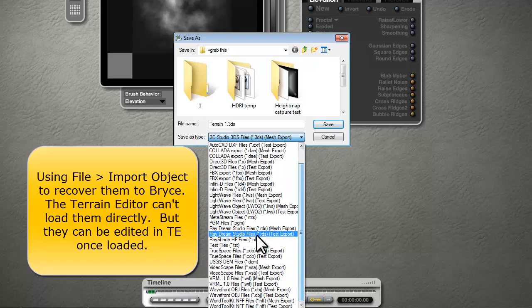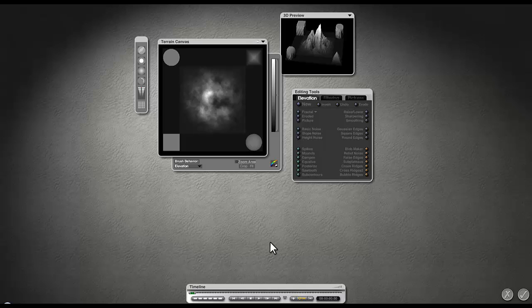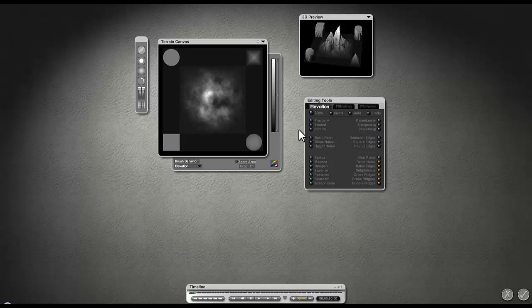So some of the height map formats do work, but the importer for the picture is very particular about what it accepts, and it won't necessarily accept back what you've exported out, but other software will accept it. What you need for the picture ideally is either 16-bit grayscale TIFF or 16-bit grayscale PNG. The PNG definitely works. The TIFF, I recall from the beta testing, was the other specification, but there's not much software out there. I know that PaintShop Pro won't do it, and I just tried Project Artist and that doesn't seem to handle it. The 16-bit grayscale resolution seems to be quite a rare format, so all in all it's a problematic thing passing these height maps around between Bryce and other software.